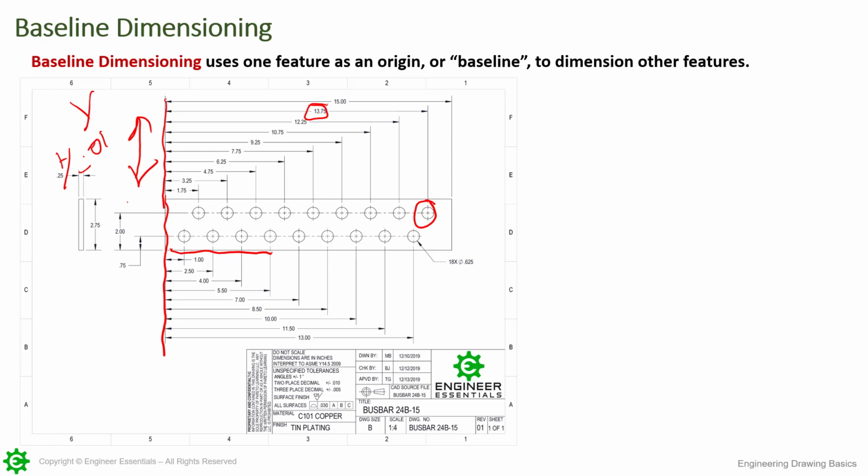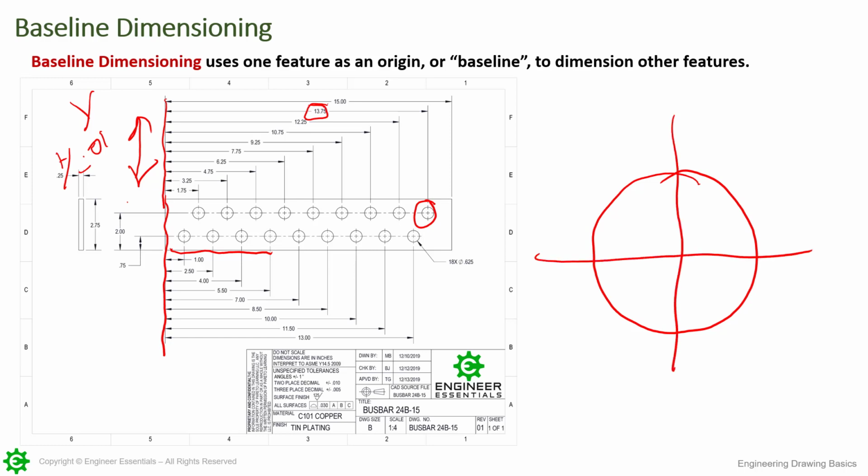If you look at the hole and kind of blow this up and look at it, here's our crosshair there. This creates the square tolerance zone that everybody talks about for coordinate dimensioning. This is the whole reason why we use GD&T, or position tolerancing, for this, is to get a circular one. But this gives us that tolerance value here that is a total of 20 thousandths, right?